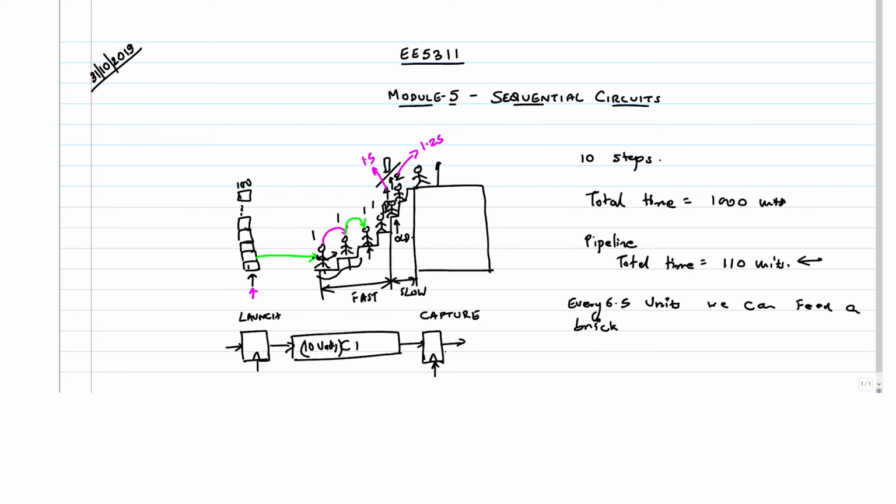If I want to pipeline this just like the way I did there, what I would do is break this guy now. It's like each guy now is a logic gate that has a delay, and that's 10 units. Of course, it's partitioned as 1 plus 1 plus 1 plus 1 plus 4 plus 2 plus something maybe. So I'm going to break this down into C11, and put another flop in between.